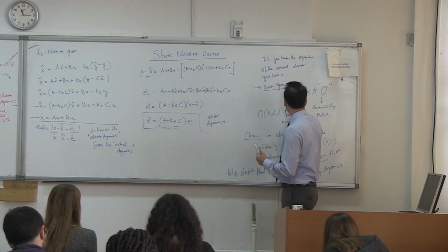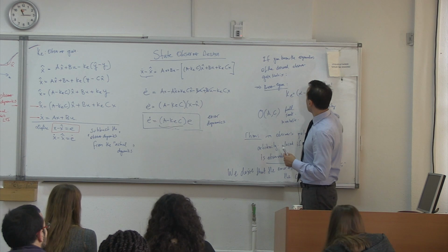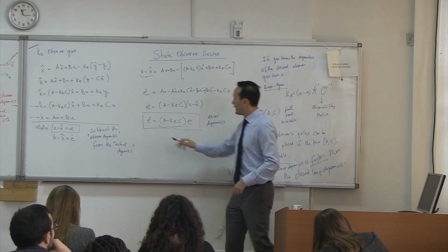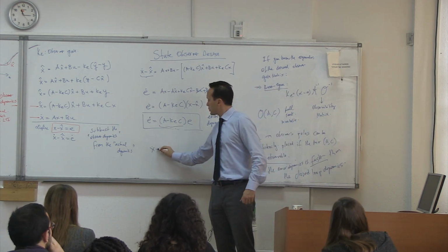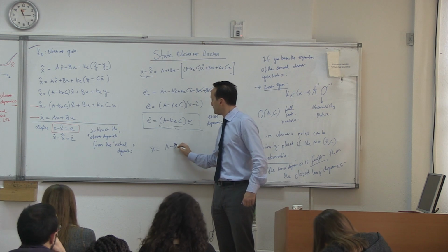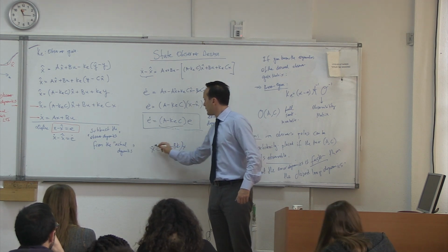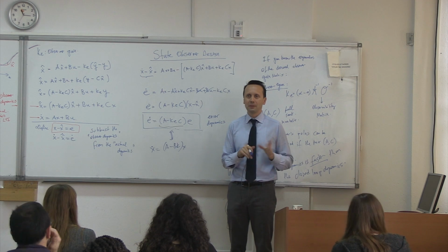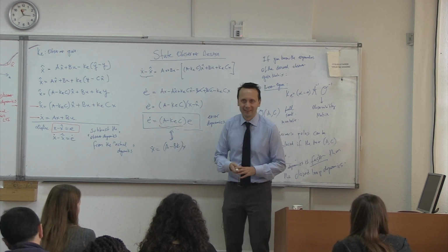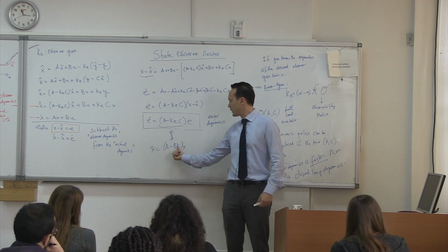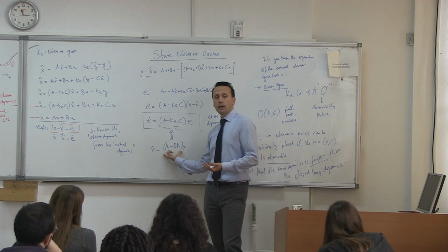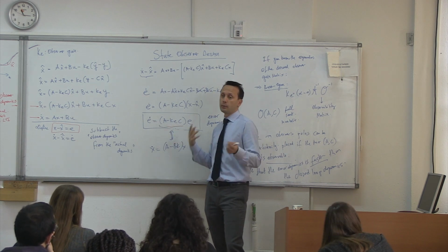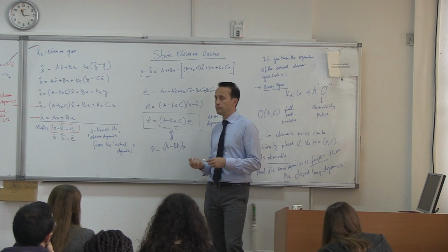But still, I want you to see that there's a duality between the controls problem and the observer problem. Just based on the fact that the closed loop system looks like this, A minus BK times X. Duality is not the right word because duality has a different meaning, but you see how similar the problems are. Okay? Here you're trying to find the K to match a certain closed loop system. Here you try to find K to match the error dynamics the way you want. Is that good?